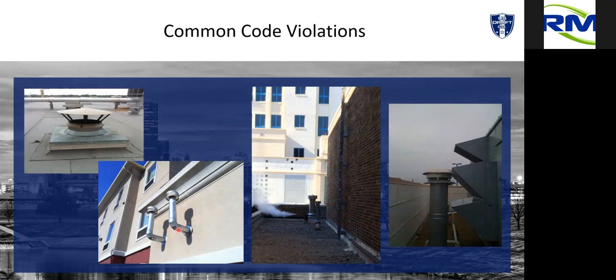Over here, we call this the Texas Special. In the state of Texas, where we live, there are a lot of 3-story apartment buildings with single-story mechanical rooms. They take their water heaters and sidewall vent them with V-vent, which is a violation for Category 1 appliances. So we say you can't terminate V-vent on sidewalls. They say, okay, fine, we'll put a 90 in a piece of pipe with a cap. I'll say, that doesn't work because you haven't exceeded this wall by 3 feet. So then they try to run V-vent up the side of the wall and exceed that, but code says you can't have more than 5 feet of V-vent exposed. There are a lot of variances they've tried to overcome it with another piece of pipe, and it just doesn't work. The other solution is to just put a fan on each of these and you're done. Same thing with this one.